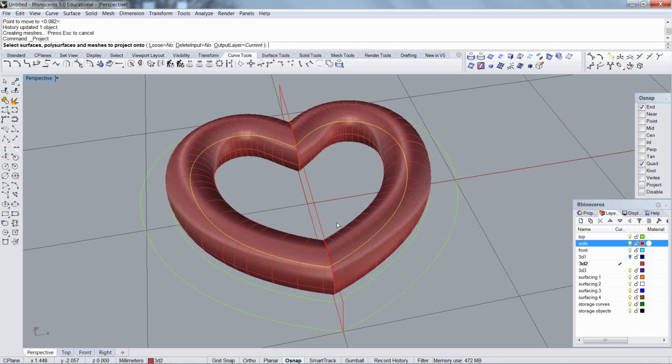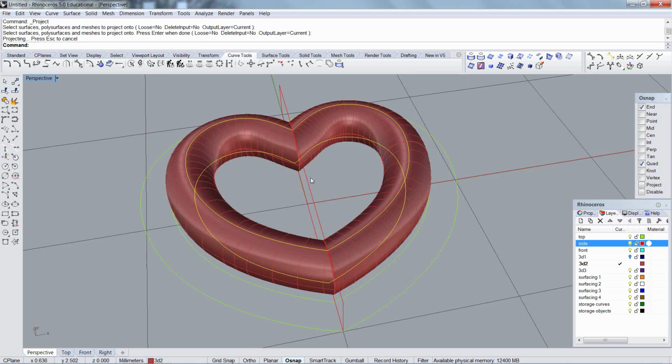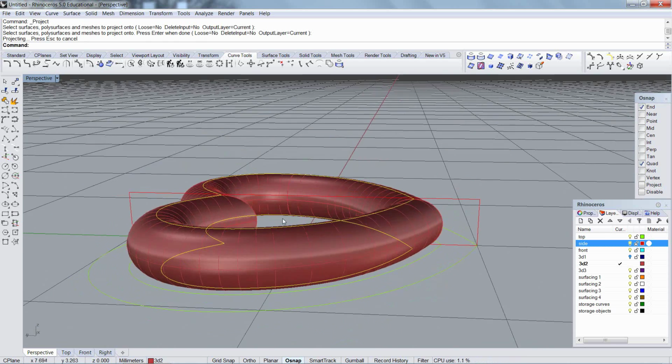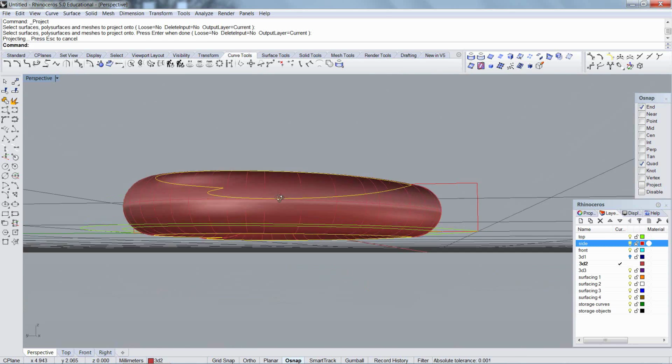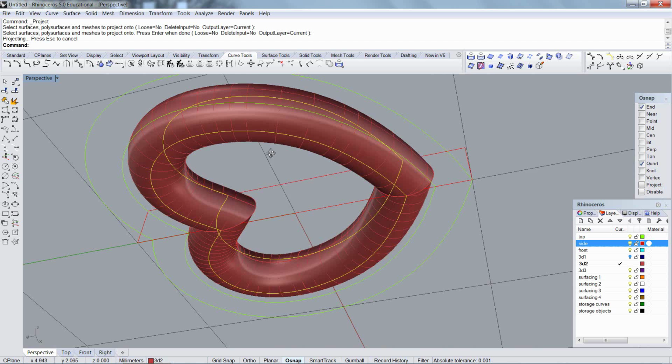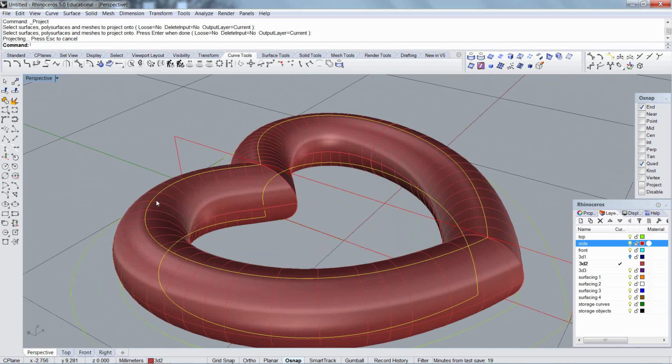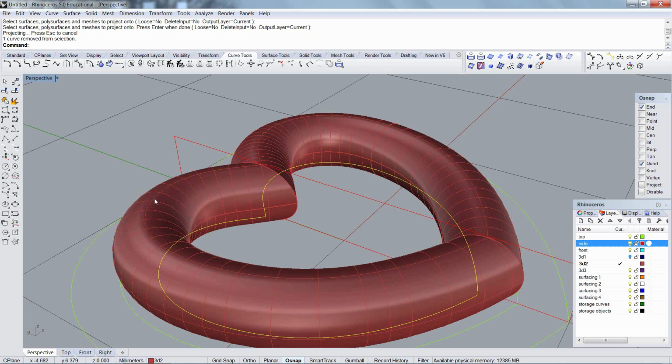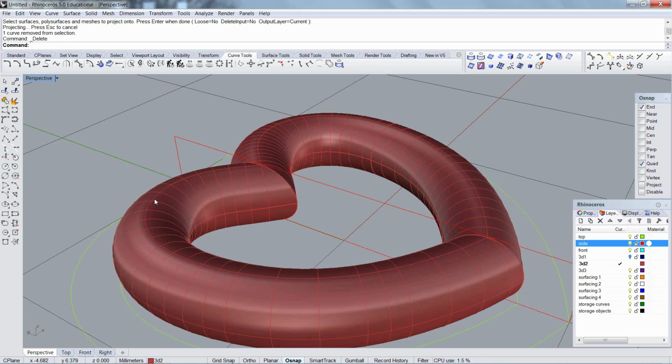So here we go. It gives me 2 because in the projection it would intersect with that pipe both on the bottom and on top. Going to extract, going to click and deselect the one I want to keep, and then delete the other.